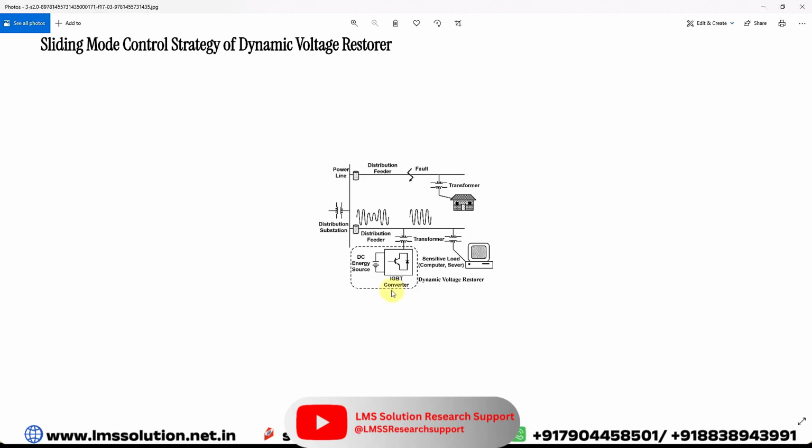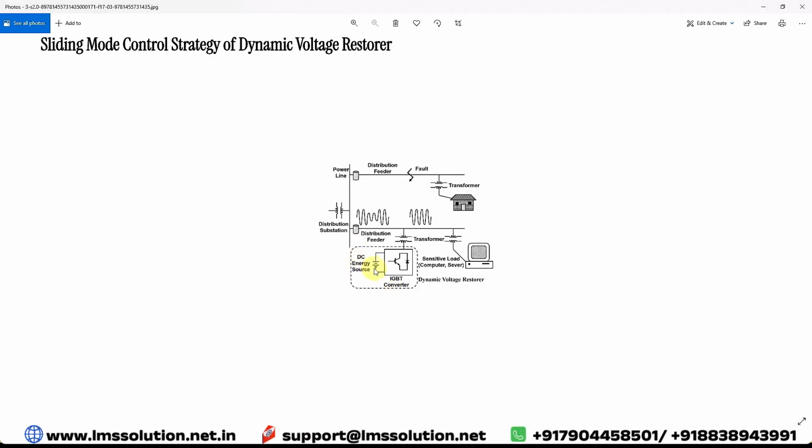This DVR consists of a DC energy source and an IGBT converter. Here we need to measure the distribution feeder voltage, and based upon that voltage, the DVR is going to inject some voltage into the system in order to maintain the sensitive load voltage at 1 per unit. So this is the use of this dynamic voltage restorer.